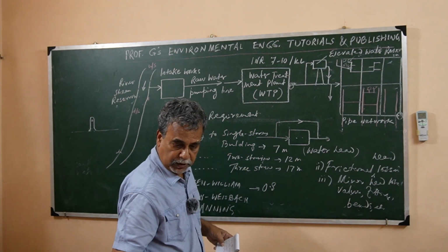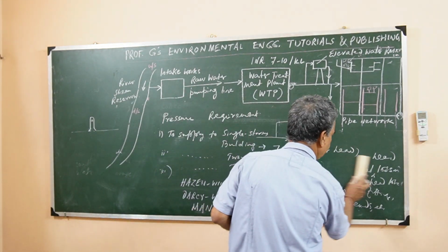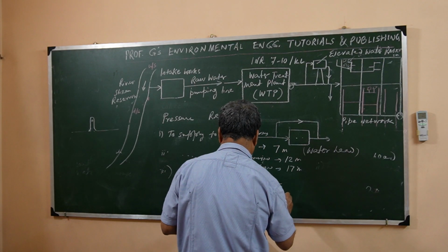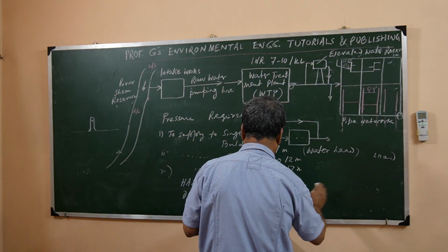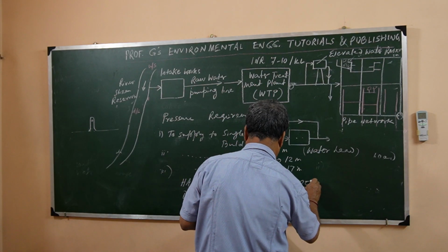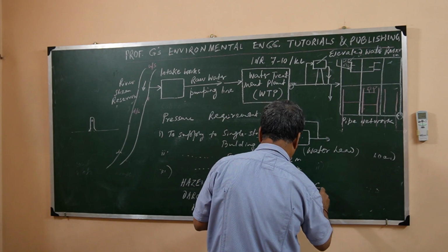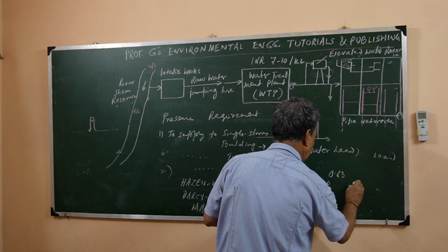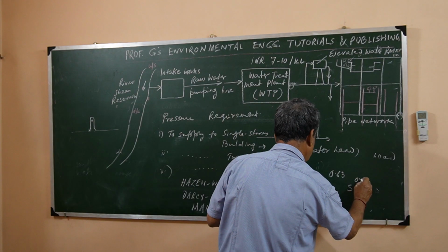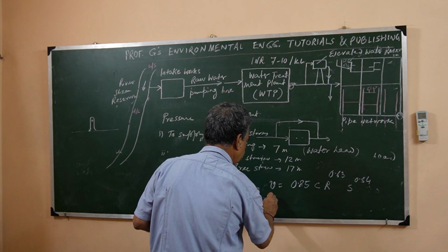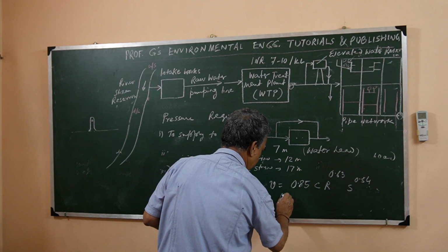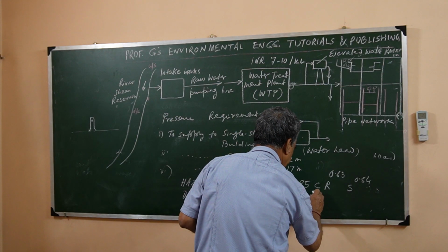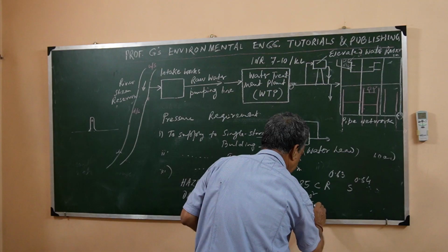So this actually, Hazen-Williams is point. That is a. Let me erase this one just to have more space. So that is the velocity of water through the closed conduit pipe also, that is 0.85 C, that is the Hazen-Williams coefficient, R to the 0.63, S is the hydraulic gradient. This is the Darcy-Weisbach, that is, hf is equal to f L V square by twice g D.